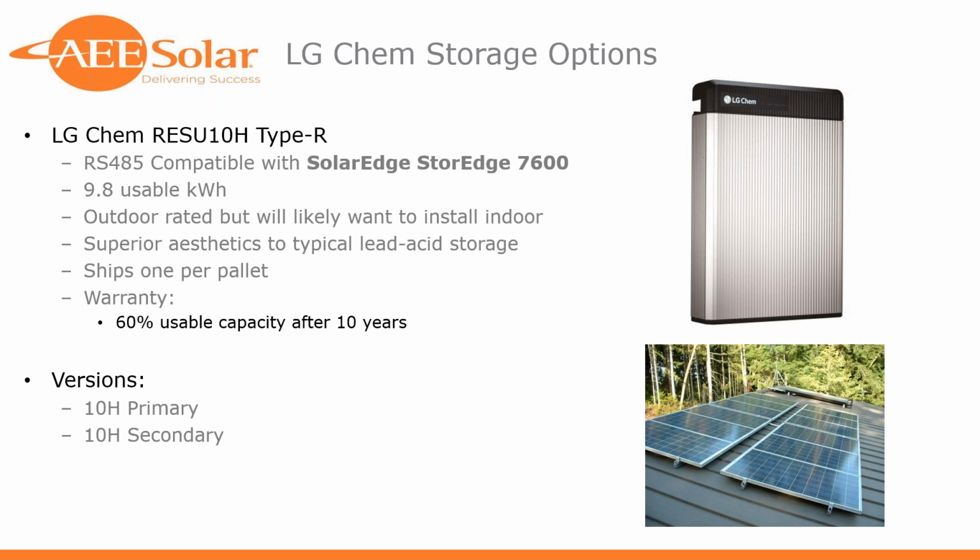So two, maybe versions isn't the proper word to use, but two models of the LG Chem Resi 10H Type R. There's a primary, and there's a secondary. Secondary being if you want to do a larger 2-unit system, so you want to pair two of these batteries for one storage inverter.